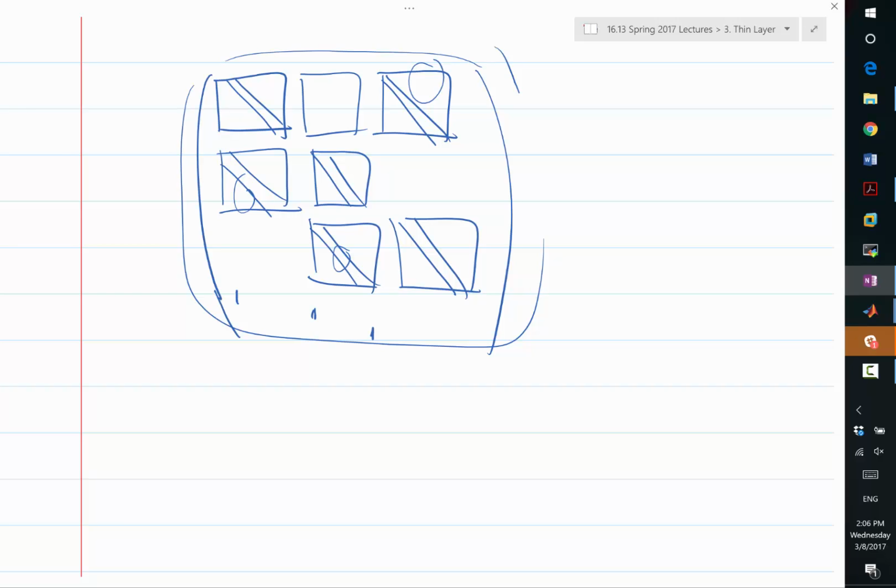Then they are coupled with each other on the off-diagonal terms. For example, if the boundary layer solver is represented by what I'm doing here, instead of the integral formulation we're going to introduce later, we're just solving the thin layer Navier-Stokes. Then the coupling term from the thin layer Navier-Stokes to the outside would represent the numerical integration, right?